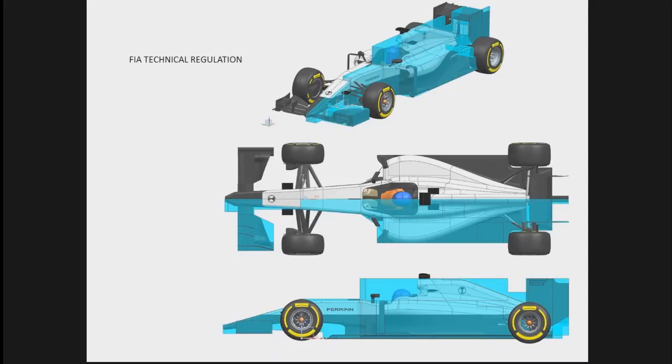Okay, the simulation was done on SimScale. This is an online simulation platform where you can do CFD simulations, web-based, cloud-based, and there you can also, I mentioned it 2 or 3 times already, access all the simulations and analyze them yourself. And meshing was done with SnappyHexMesh as well as the solving with OpenFOAM. This is both open source software, which is also used in F1. I'm not sure, but I'm quite sure that Sauber is using, for example, also OpenFOAM. And yes, that's the software which was used.